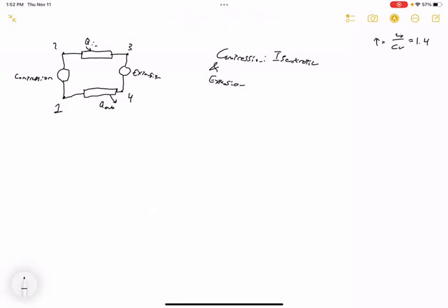Okay? Now, whenever we have a polytropic process with air where N is 1.4, this is what we really call an isentropic process. All right? So mathematically, that's the difference between a polytropic and an isentropic process. A polytropic process could have pretty much any N value, but the isentropic process has a value specifically of Cp over Cv, which for air is 1.4. And we're going to assume air in most of these cycles, including this question.